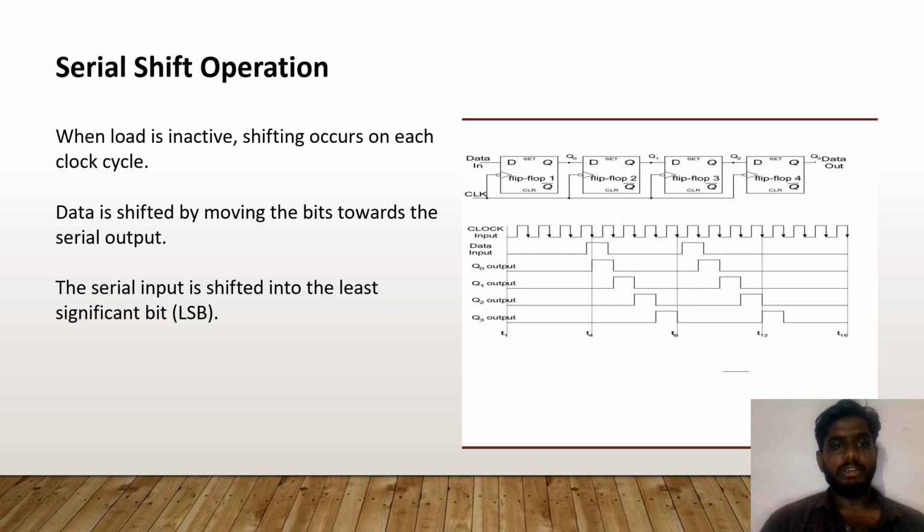Serial shift operation. When load is inactive, shift occurs on each clock cycle. Data is shifted by moving the bits towards the serial output. The serial input is shifted into the least significant bit, LSB.